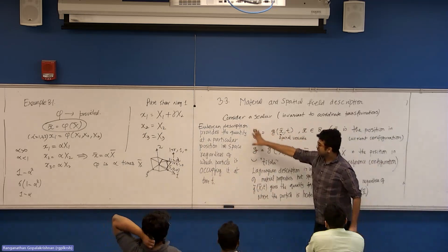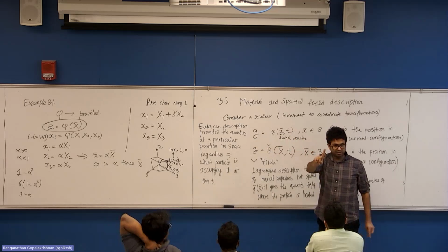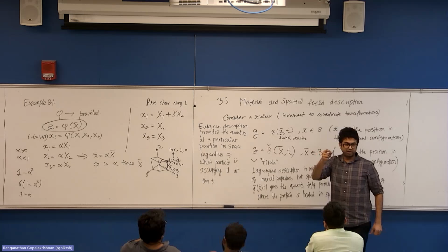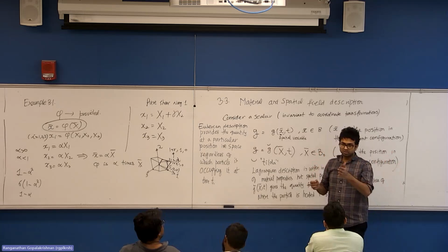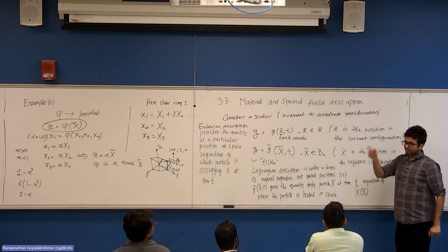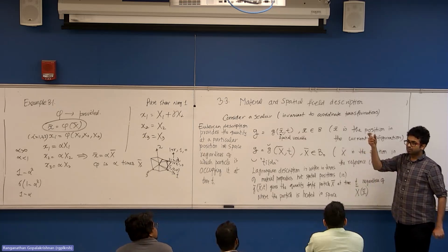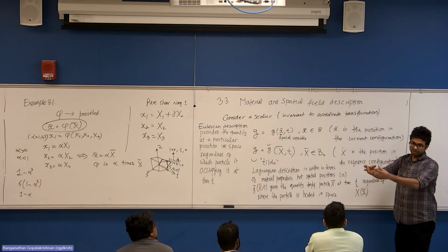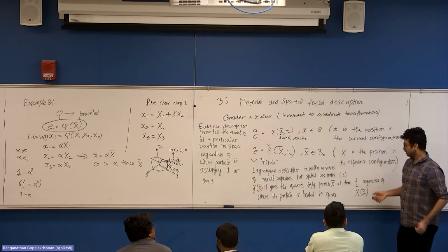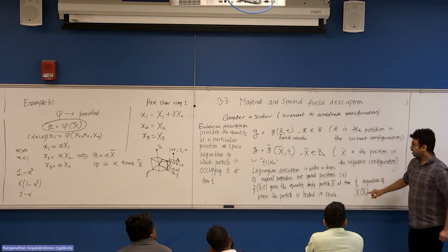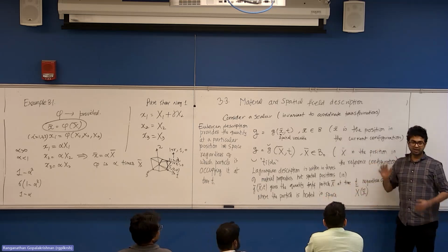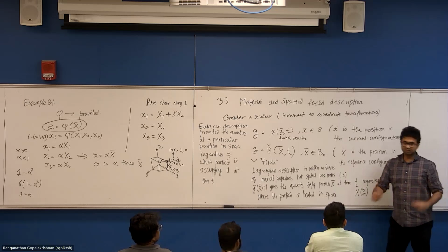Eulerian description is about space, about a single point in space. Once you define the point, material comes and goes. Lagrangian description is about tracking a certain group of particles, this group of atoms which you call a particle, wherever they are distributed, and how they change shape, how they deform, and so on. It is not about space. Regardless of where the particle is, that is immaterial. It is about what the shape is.